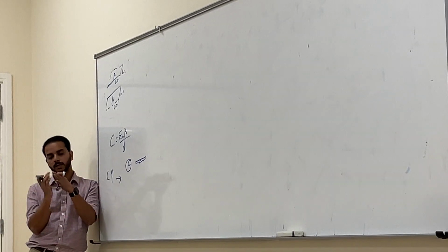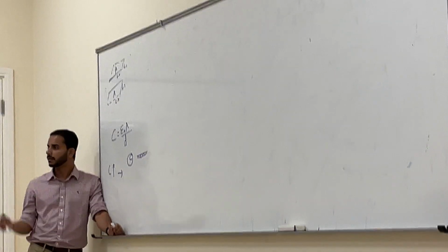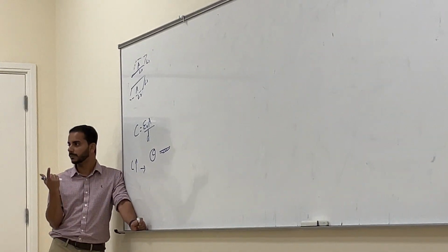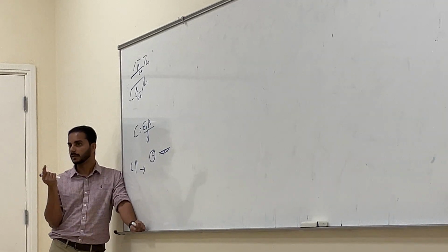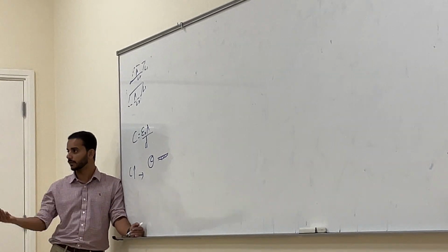So you have to keep a separation of some minimum. If you want to apply something like 1000 volts in vacuum, you have to keep a minimum of 1 millimeter, right? In ambient pressure, we have a lot of nitrogen, we have a lot of gases.